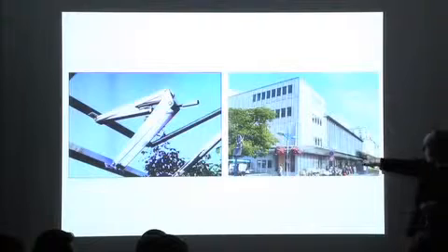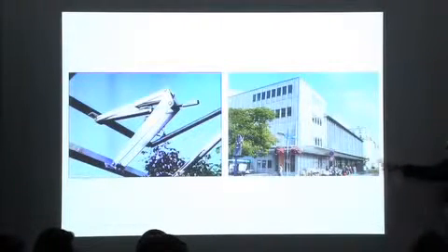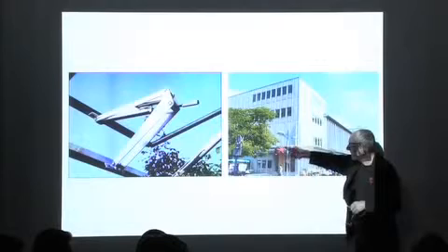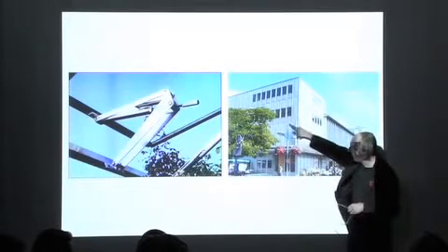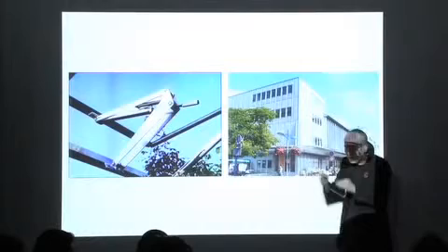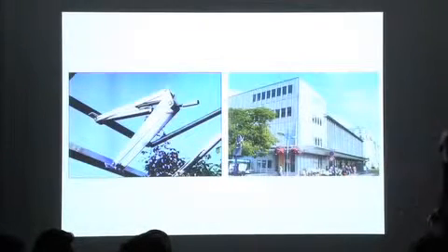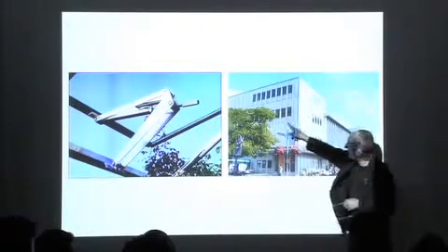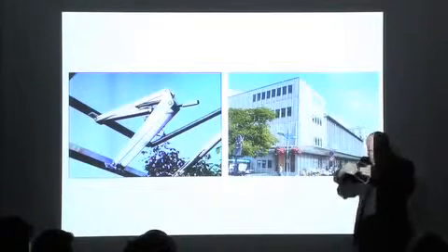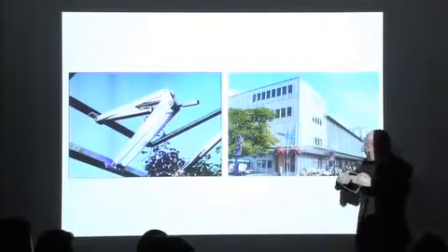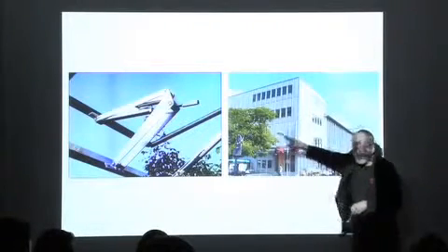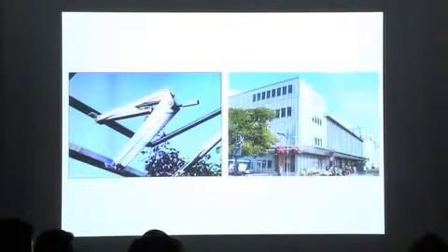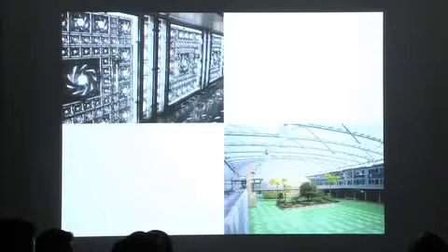And this is a building by Jean Prouvé, where all the cladding panels do the same sort of thing. Rather than what we do now, which is expansion joints to allow differential movement for different materials, Prouvé just said, well, these panels can sort of pop. They curve out when they heat. So we don't need to have expansion. So it's a very dynamic facade. It actually changes shape when it gets hot. When it warms up, the whole facade slightly pops out and exaggerates. Solves the problem by a state change material.